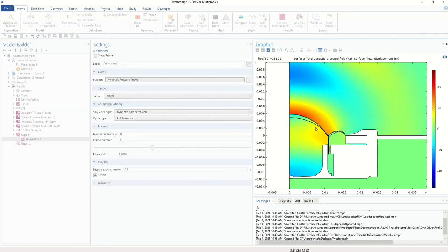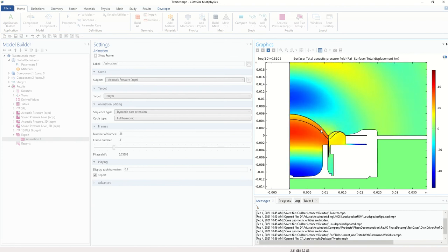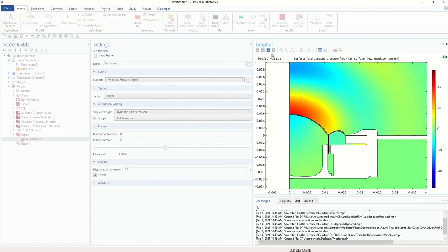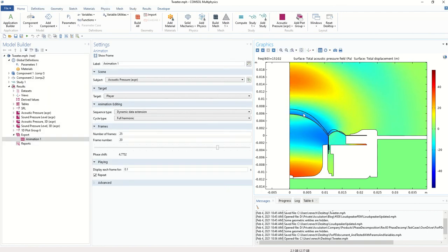And you can see we have a really exaggerated view of the dome here. And that's sort of what you have to do, because in these frequency sweeps, actually nothing moves. Everything is linear, so nothing moves away from a certain starting position. So that can sometimes mess up engineers a little bit. But you have to know what you're doing and what you're seeing on screen.